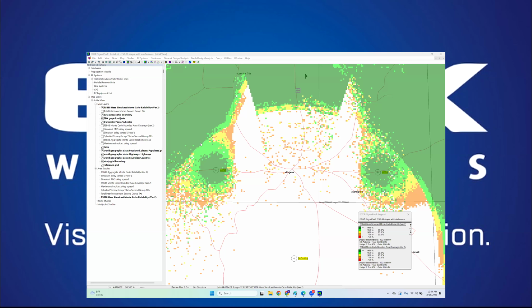Or if the manufacturer gives a spec, I would say that overrides the document. And if you have the ability to bench test that equipment on a fading channel simulator in the lab, then you can create your own simulcast signal versus delay file based on real measurements of how that receiver performs under different channel conditions.